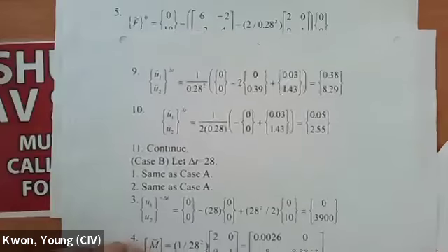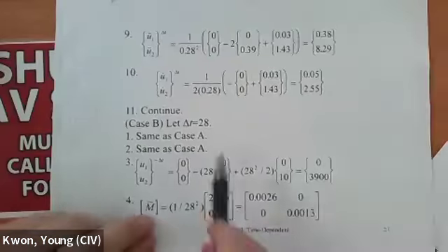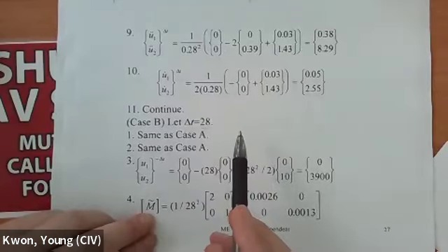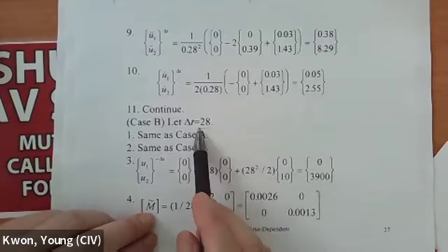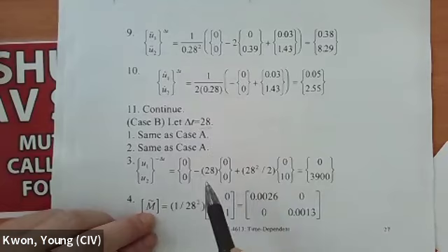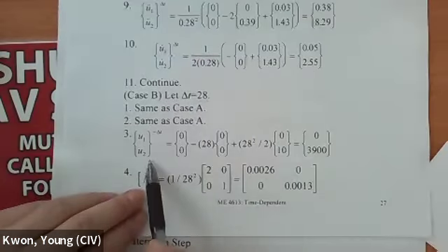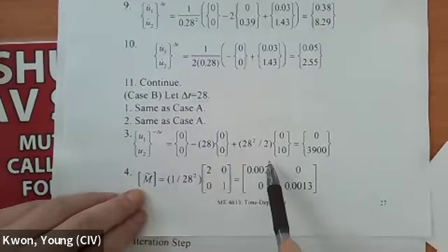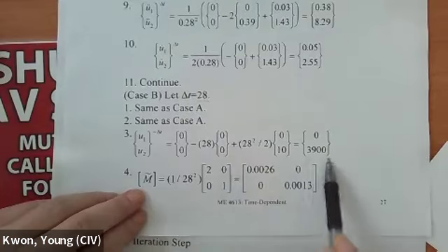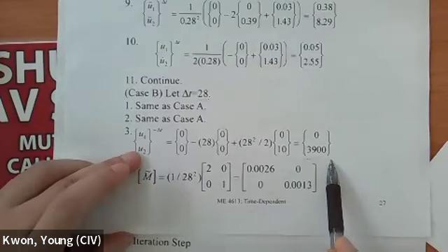So far, so good. Now, if I pick a large delta t, 28, much larger than the critical value. The reason I pick a larger value is that I'm going to show you that this is going to explode very quickly. Then the fictitious solution is going to be from here. If you plug in delta t, you got that. That's the fictitious displacement.